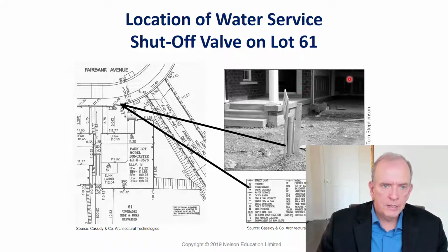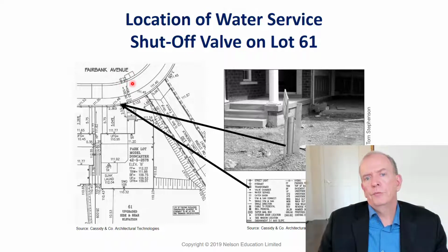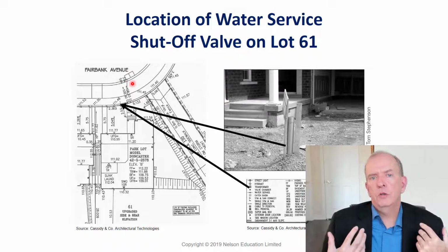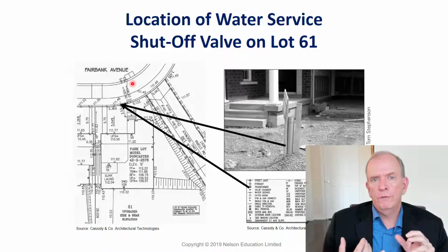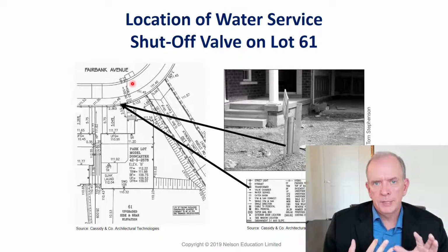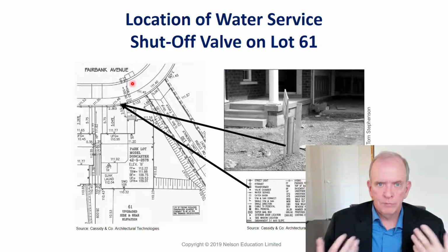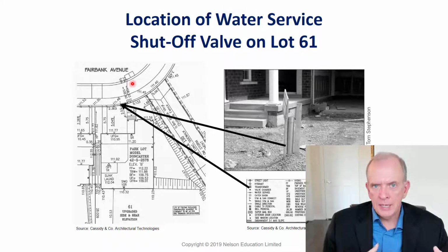It also says here the stormwater and sanitary sewers for the street, where they are. So in a subdivision, you're going to have two sets of sewers. You're going to have one for stormwater and one for sanitary. The stormwater is taking more clean water from a rainfall, and taking that into the drain system. It's going to go into the tributaries, into the rivers, and then it's going to go out into the lake.